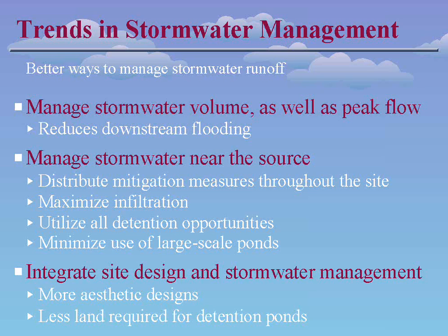We're looking at techniques for distributing the mitigation measures throughout the site. Rather than just using centralized detention, we are now trying to infiltrate water as much as we can, either to prevent it from running off initially or infiltrate it through other measures within the site. And there are, as you know, a lot of different techniques that are coming into play for this kind of more elaborate management.